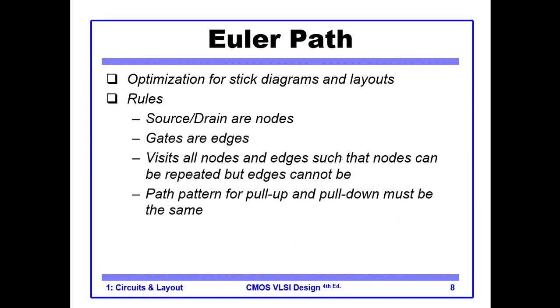Now let's discuss something that is called Euler's path. What is an Euler's path? It is basically an optimization for stick diagrams, or for that matter layouts, because a stick diagram is a simplified model of a layout. And why do we need this Euler path?